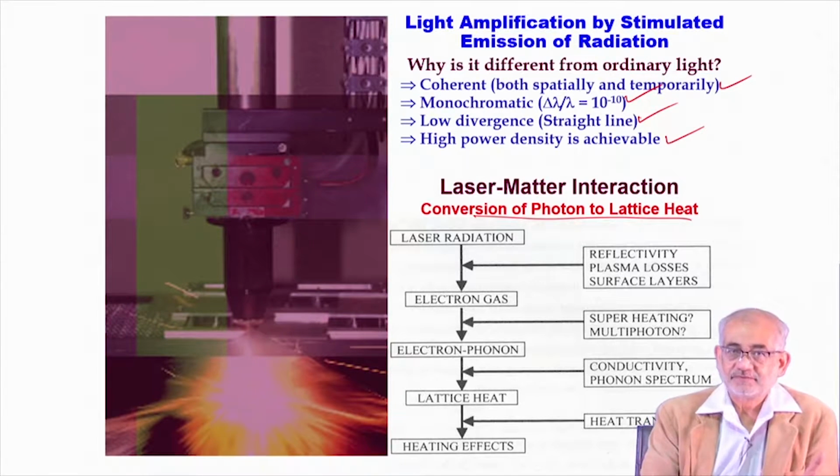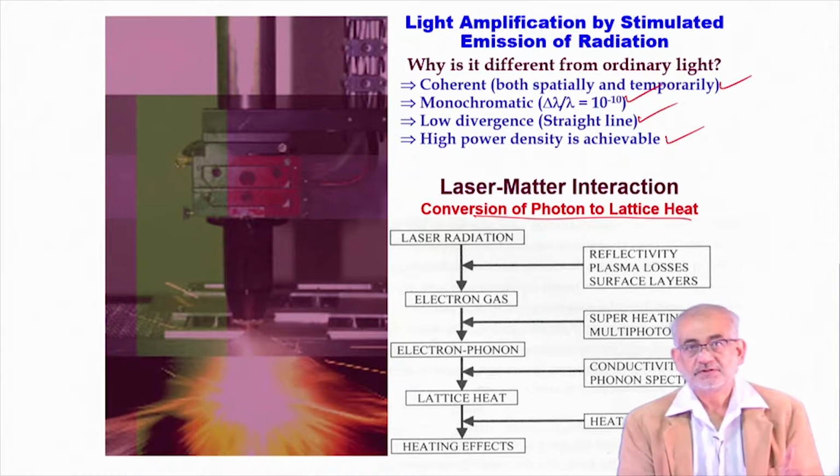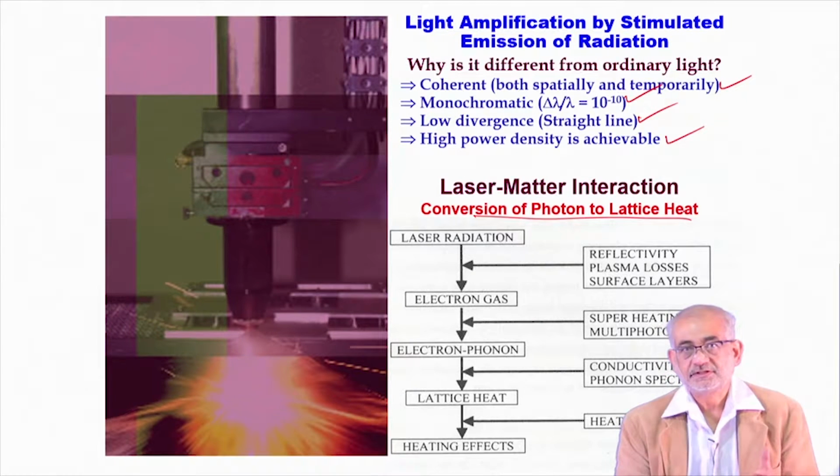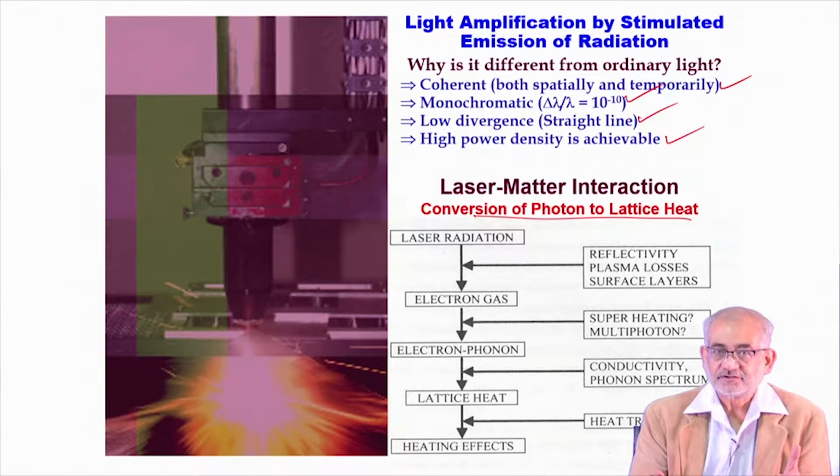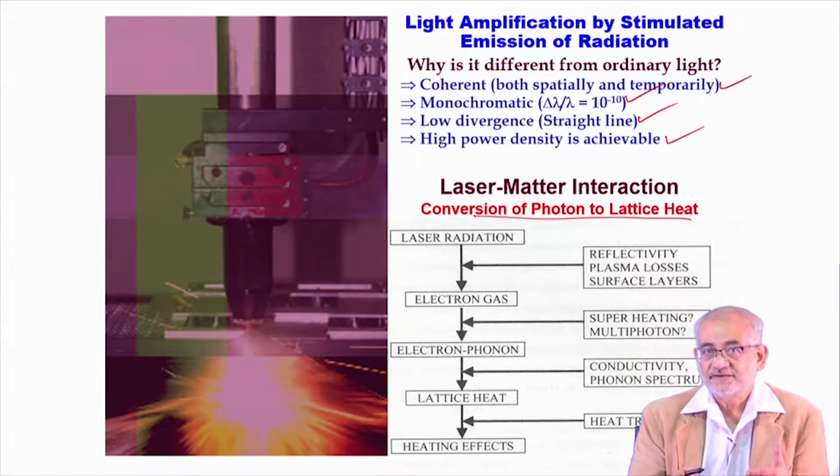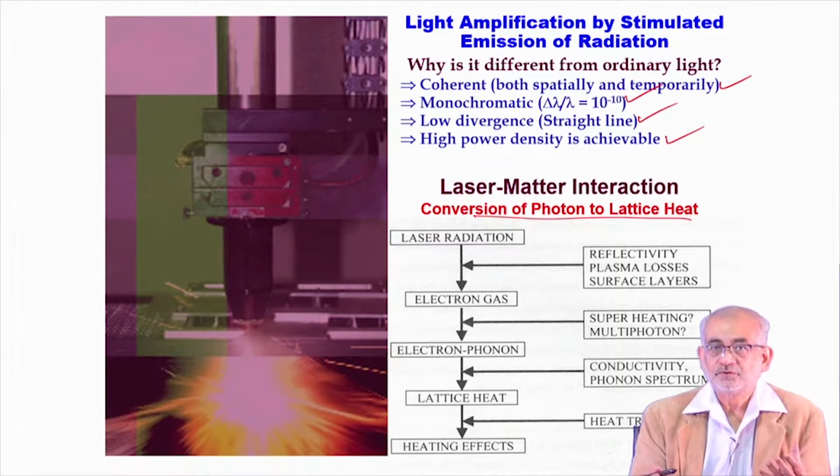So metallic and non-metallic, to make it much simpler. Metallic materials will have a free electron cloud available on the surface. So incident electromagnetic radiation or laser will always have an opportunity to interact with the free electron cloud, and the majority of the incident wavelength will actually have the possibility of getting reflected back. So you couple only a few percent of the incident energy onto a solid metal.